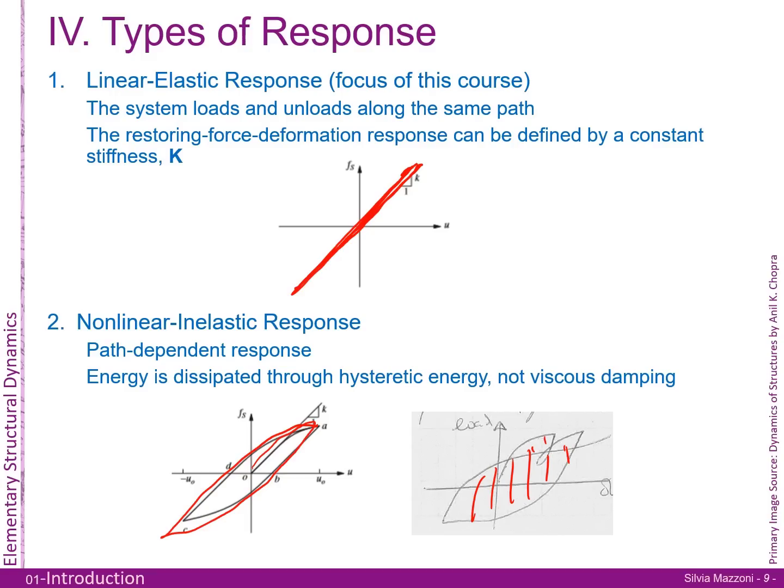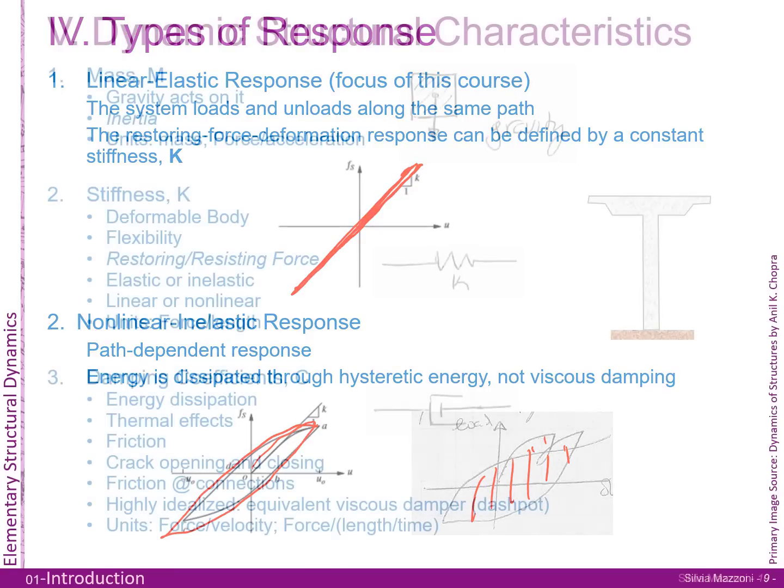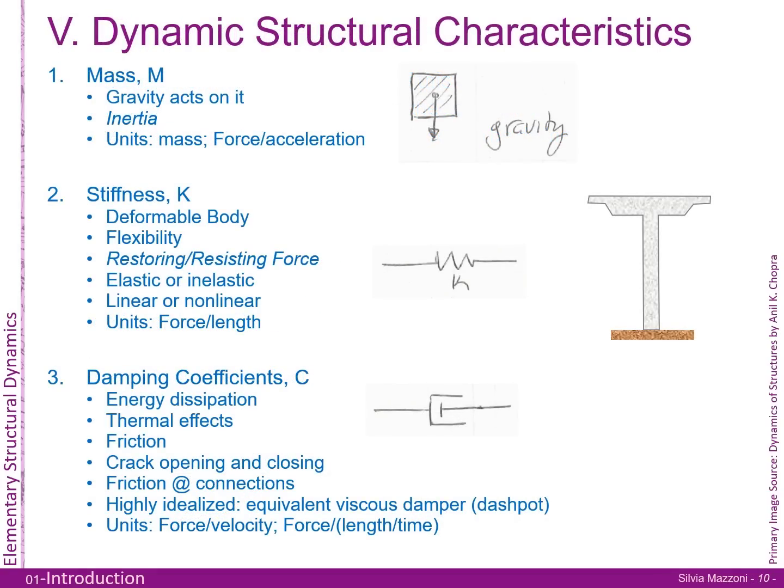But if you don't have any energy dissipation, your system is going to keep on oscillating. And the energy dissipation actually reduces your deformation demands elsewhere. So it's really important to understand nonlinear response and being able to understand where you want to concentrate what we call hinges in your system. So you can't really live in denial of it, so you might as well take advantage of it. And I know it seems iterative, but I think it's important to focus on each one of these components as the different dynamic structural characteristics of your system. So the very first one that we're going to talk about is the mass.